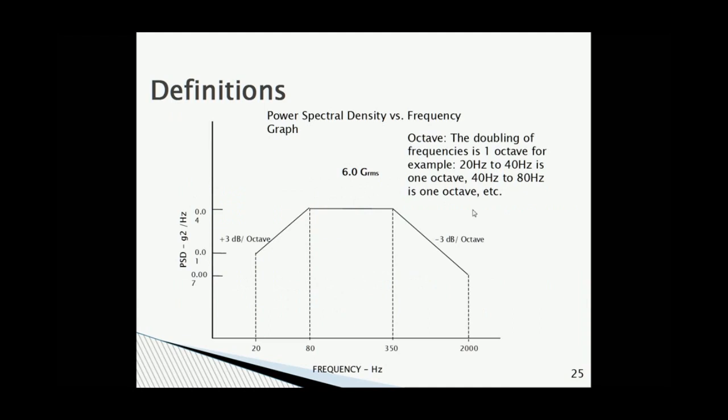Okay, let's go ahead and look at this graph. Should look familiar to you. Here is a random vibration graph. Now, random vibration, unlike sine, does not occur at a single frequency at a time. It occurs at multiple frequency points simultaneously. And the amplitude and the phase of these vibration points at each frequency is random. Now, this is more representative of the real world.